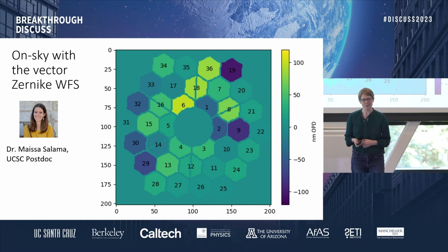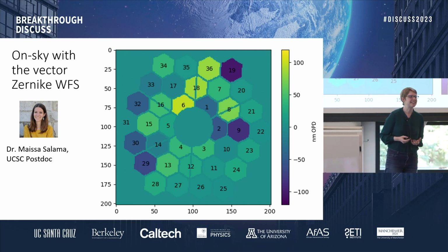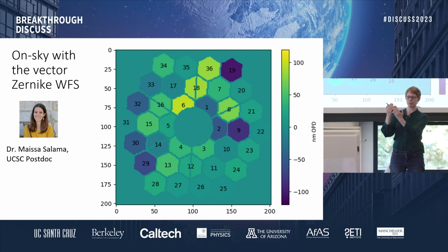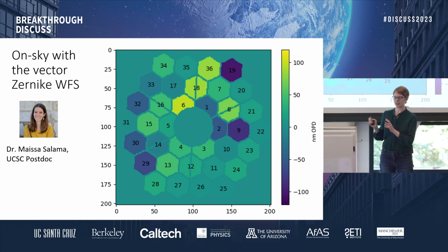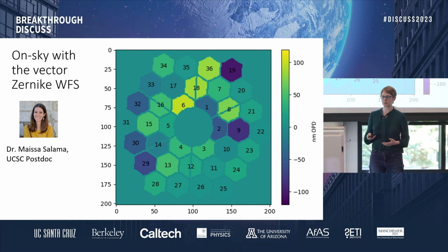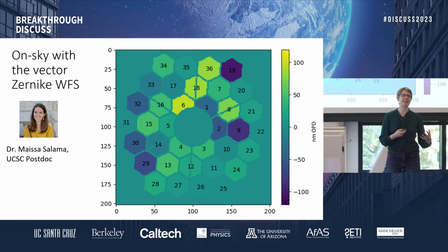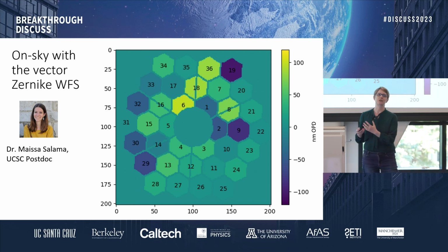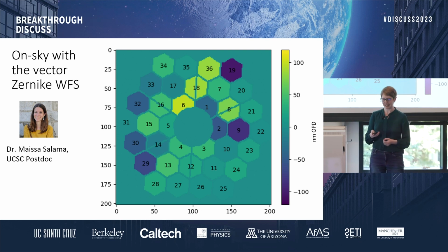What really excites me about this Zernike wavefront sensor work is that even though we have very different regimes of primary mirror stability to deal with on the ground and in space, we're dealing with all the same problems as the space-based telescopes. We're dealing with how well we can phase up the mirror using a set and forget method, which is what we do at Keck currently, and then what's the benefit of dynamically controlling the mirror using something like a Zernike during a science observation.